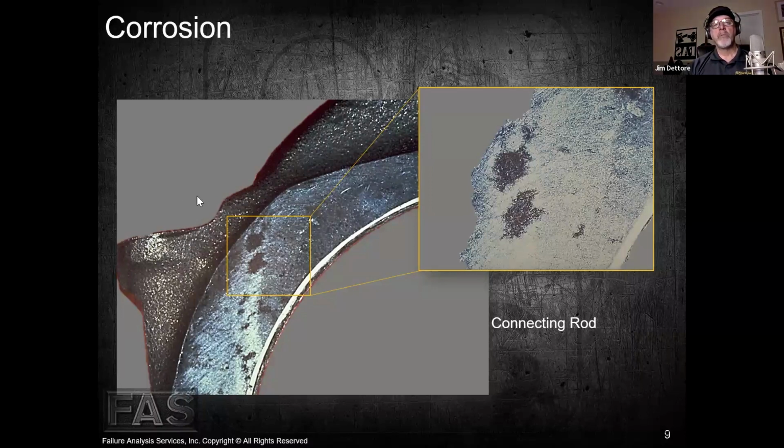So we also have some compressive stress here because of the bolt compressing those areas down. And then stress concentrators here. And we have seen things like this, as well as some other problems in these areas cause connecting rod failure, which inadvertently results usually in a hole in the block.